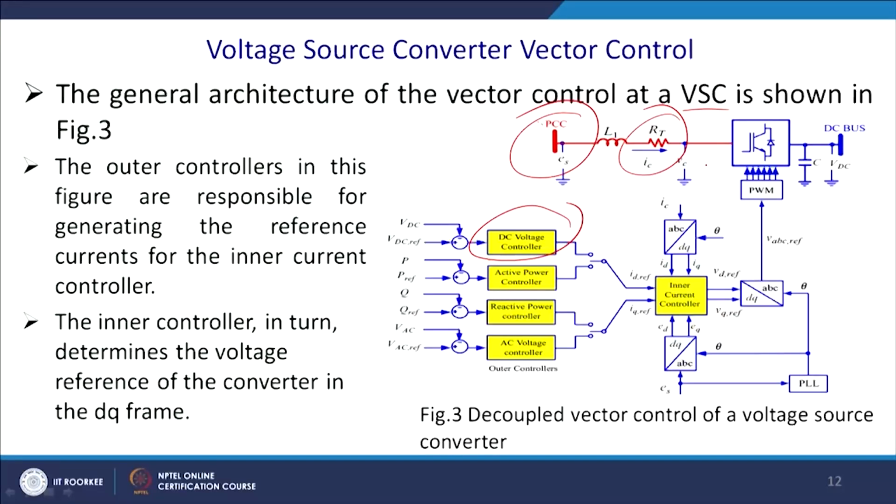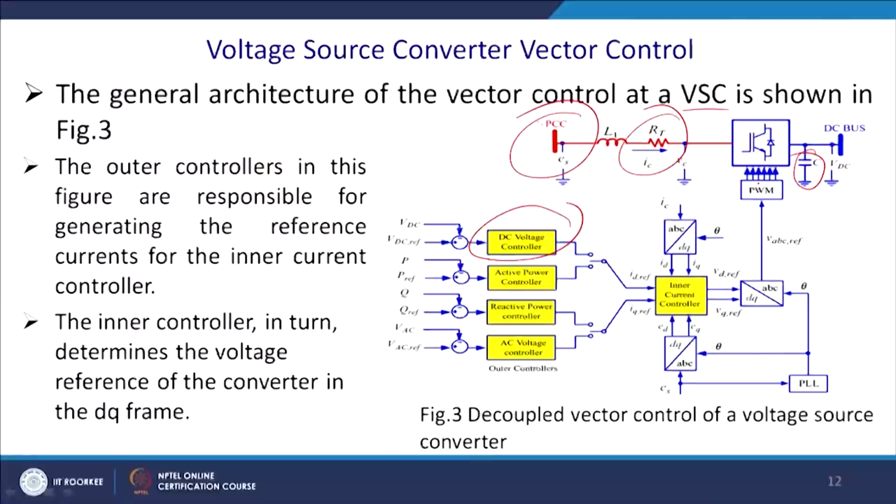Even if you withdraw the PWM pulses, you will get some voltage here. That will be the 3 phase rectified voltage, the 6 pulse voltage, 3√3 Vm by pi. So, you have to take it 20% above by switching, because essentially it sees a boost converter if you look through that side.